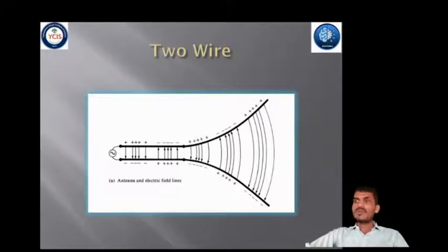If we assume that the voltage source is sinusoidal, we accept that the electric field between the conductors is also sinusoidal, with a period equal to that of the applied source. Now the relative magnitude of the electric field intensity is indicated by the density or bunching. So we can see that different numbers of bunches are generated by the charges, with the line of force arrow showing the relative direction, that is positive or negative direction.